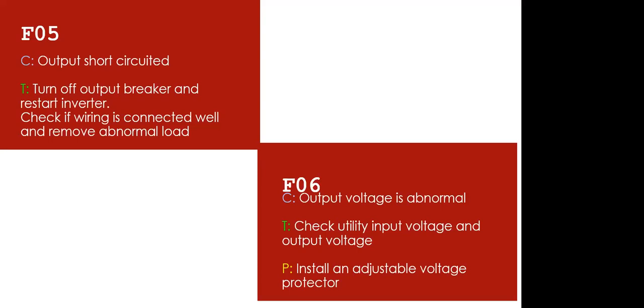After doing all that, check all that is supposed to be checked, maybe in your appliances and your input connection. You check everything, then you turn on your battery breaker first. When you turn on the battery breaker first with nothing connected, the inverter will run successfully on battery mode if the fault is not from the inverter.